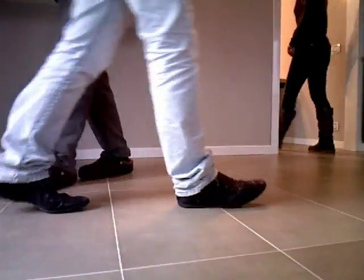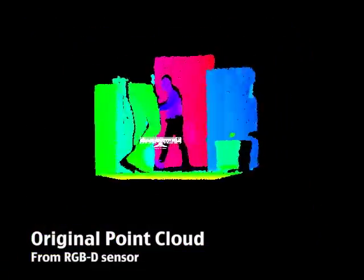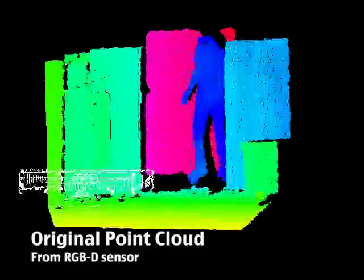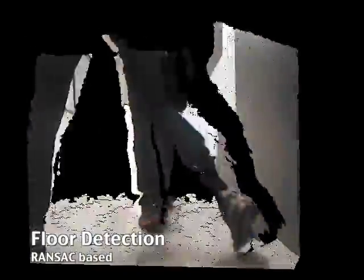In this work, we detect and track humans in these challenging conditions by means of a Kinect depth sensor using the TurtleBot as an example platform. First, 3D points farther away than 3.5 meters are discarded. The resulting point cloud is downsampled using a voxel grid filter. This optimizes computation times and leads to a homogeneous representation of near and far objects.